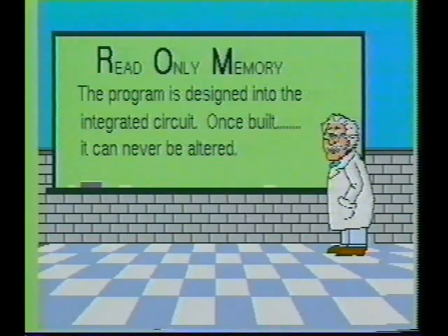In order to change the information contained within the ROM device, a new IC must be manufactured, then substituted for the old one. Since this is a time-consuming and expensive process, the read-only memory device is economically feasible only when used in large volumes for a thoroughly debugged application.